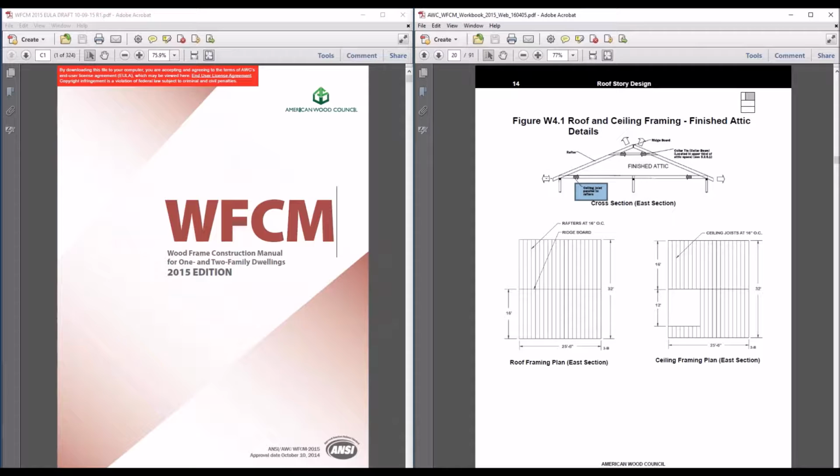The ceiling joist, and what we'll see in a second with the vaulted ceiling is a rafter tie, are used to resist thrust. You see the arrows here at the top plate at the end of each rafter, and so those tie the walls together to resist that tension load that you're going to get when you get the snow load on the roof system. So collar ties are for wind loads, rafter ties and ceiling joists are for that outward thrust.